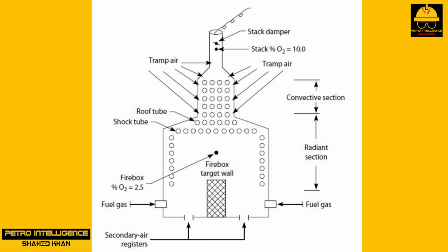We have already shown that it is wrong to operate a furnace to an arbitrary oxygen target. It is entirely incorrect to adjust the furnace combustion air based on stack gas and/or convective section flue gas oxygen readings, because as a result of the inevitable air in-leakage, the stack gas and/or convective section flue gas oxygen content does not necessarily represent the amount of oxygen in the firebox. It is also impossible to offset the stack or convective section oxygen readings to represent the firebox oxygen content, because the amount of air in-leakage varies so much with time as conditions change.